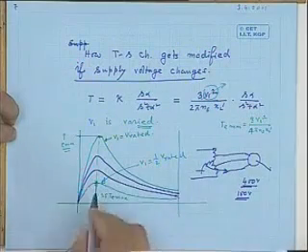The machine will slowly pick up speed. And suppose on the shaft there was no load. On no load you started the machine. Therefore machine speed will rise. And suppose the rated voltage of the machine was 400 volt. Even if you apply say 180 or 200 volt, you will find the machine is running almost very close to synchronous speed. Are you getting? Suppose the rated voltage of the machine is 400 volt. You will observe, even if you apply say 150 volt or so, not rated voltage, the machine is running very close to synchronous speed.